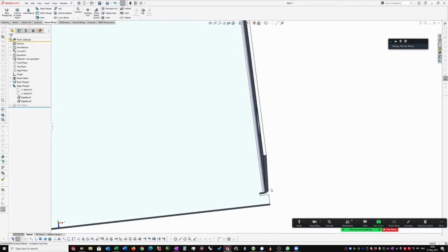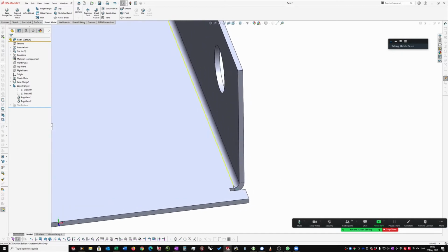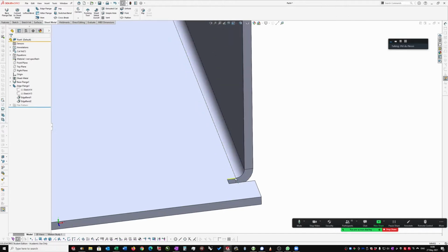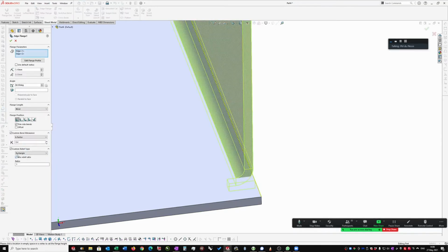It's called the bend relief because if you picture when people bend these items, the bend starts from this point, it goes around that corner up to that point, and this little section here has an enormous amount of stress. So if that weren't in place, then it starts bending this piece as well. So let's quickly go over to this, and that's called a tear. So that's a tear relief. So that's the tear like that.